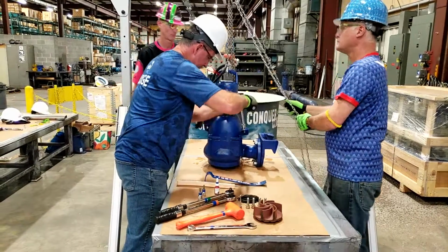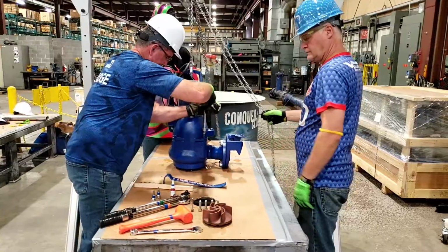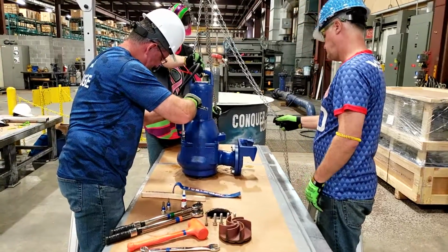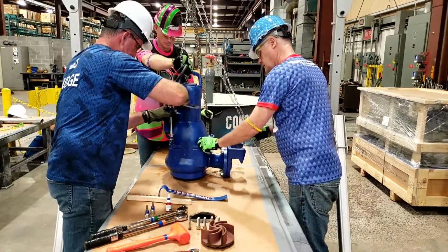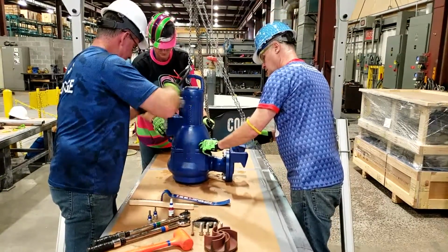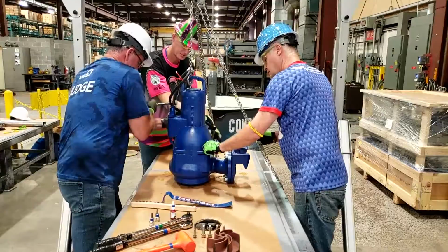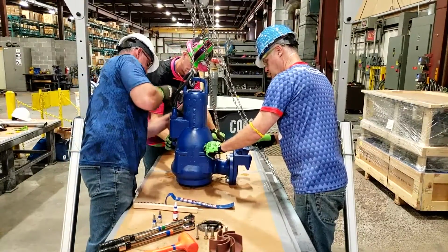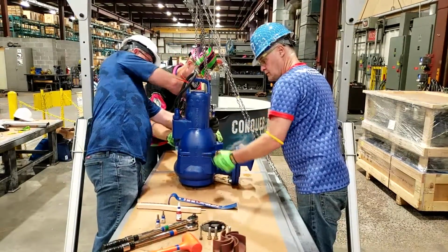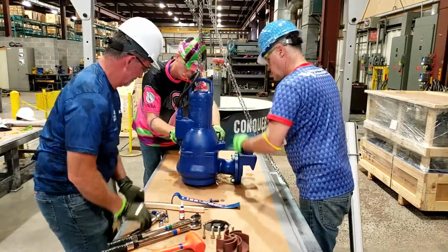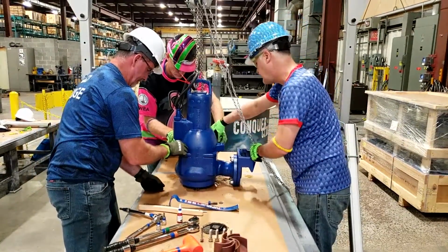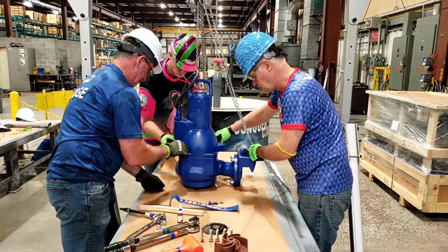You will remove the 10mm Volute hex socket bolts. They must be completely removed. They cannot just be unthreaded. They must be physically removed from the hole and placed on the table. Once the volute bolts are completely removed, you must use the gantry and hoist to lift the pump out of the volute and lower the pump back down to the table.